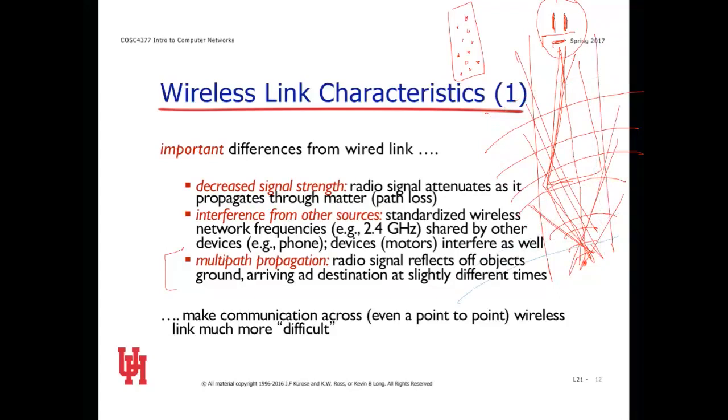And this is called multipath interference. So if you've ever driven down the high-rises in Houston listening to the radio, and you hear what sounds like it's stuttering, and you're picking up copies of it, it's called picket fencing, because the signal's coming through the gaps in the buildings, and copies of it are arriving from different places. So your radio is constantly trying to realign to the carrier.